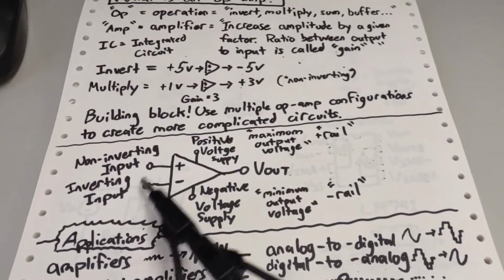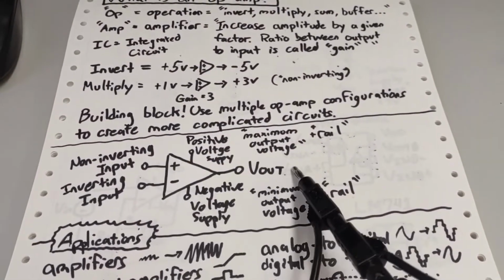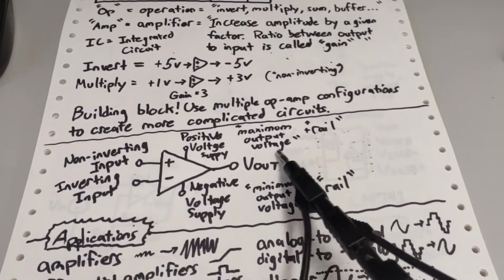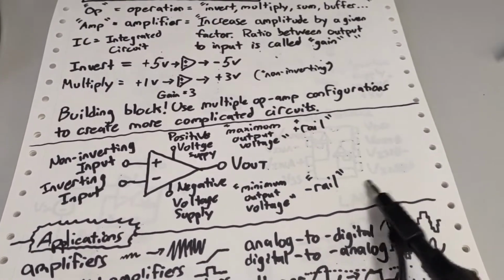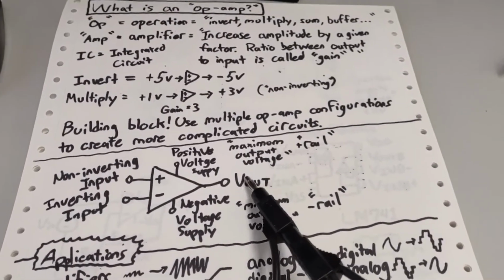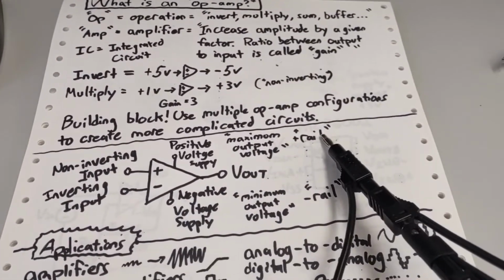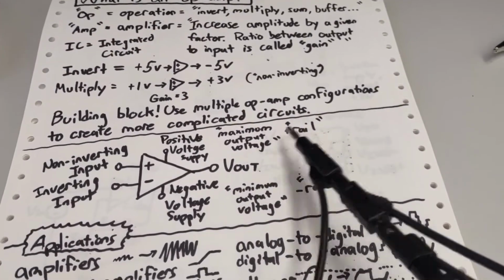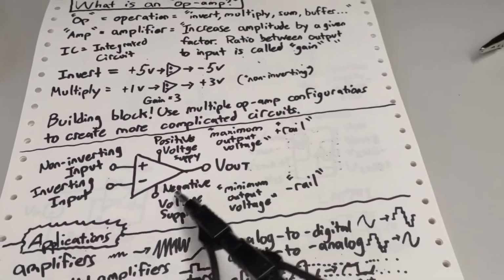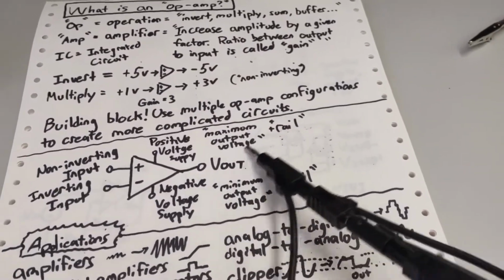So theoretically, you would have an input voltage of 1 times a gain of 400 to get an output voltage of 400, but because you have a maximum rail voltage of positive 5 and negative 5, the terminology would be hitting the rails, clipping the output voltage, or in a more obvious sense, you don't have enough voltage to recreate the signal that is being asked of it.